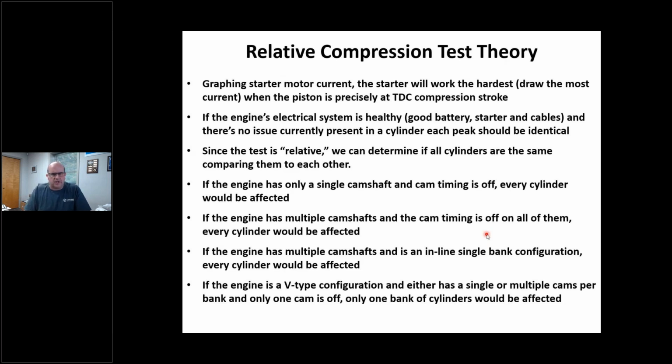And sometimes we have to check ignition timing, and I'm going to show you how we do that. But my point is this is a relative test. We're testing it relative to something else. And there's a few things we've got to know when we talk relative. If I have an engine that has a single camshaft, let's say it's an old 350 Chevy or a 6.2 diesel, or pretend whatever you want to pretend, I don't care. I've got a V-series engine or a 4-cylinder, and it's got one cam in it.